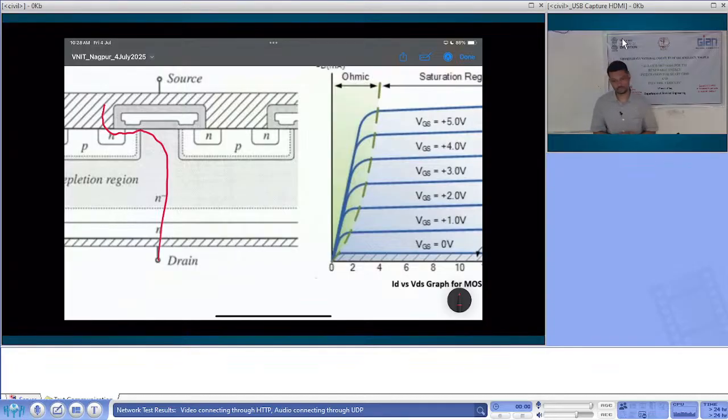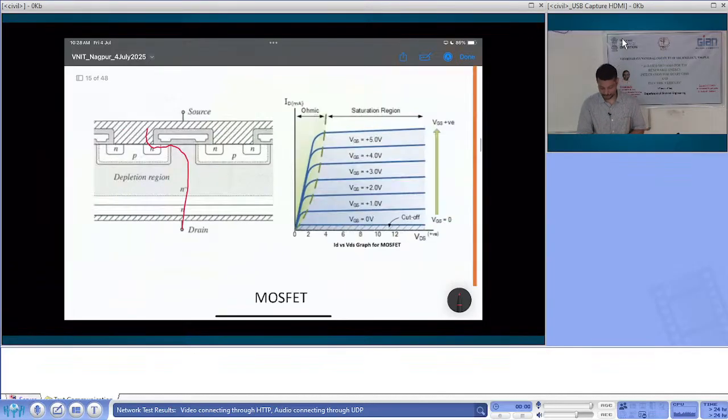So what is the difference between silicon carbide and silicon resistance? Silicon carbide can block much higher voltage, so you would have to use a lesser length of material to block the same voltage. But their resistances are similar? No, conductivity is also better. It has a higher electron velocity, I'll show that in the next slide. So it's better both ways.